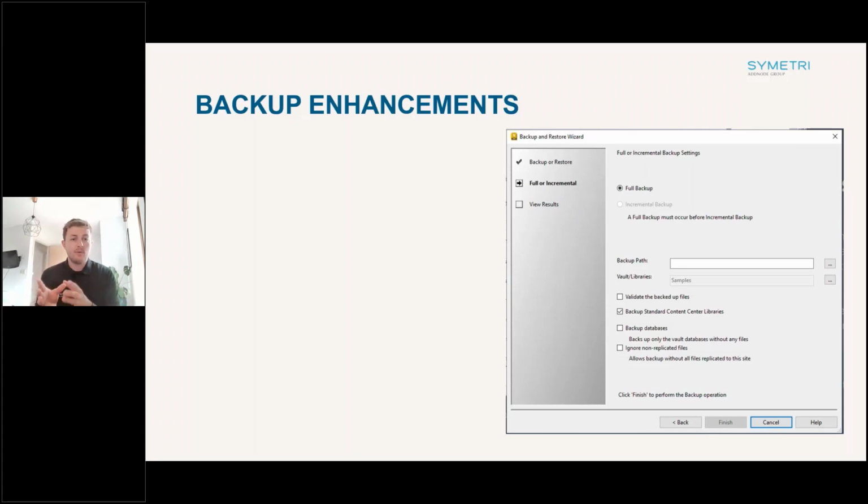You've then got the secondary area, which is your Vault file store. And your Vault file store is the component that increases the file size the most, because every time you check a new file into Vault, it's going to add that file into the file store. So for medium to large size customers, we tend to see file store sizes of anything up to 2 to 3 terabytes of data, whereas your database size on average is around 10 to 20 gig, which is going to completely vary between the size of the business. But just to give you a perspective, the majority of the storage space is in your file store.